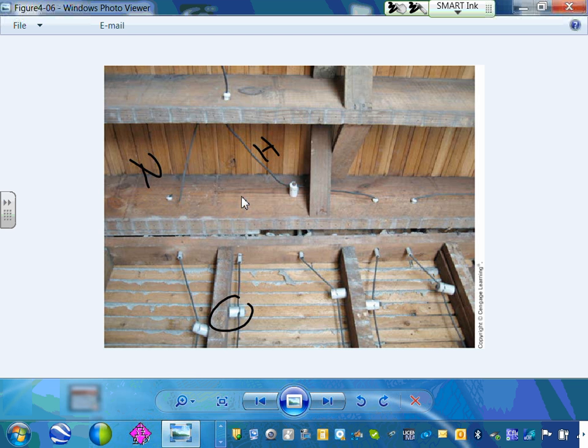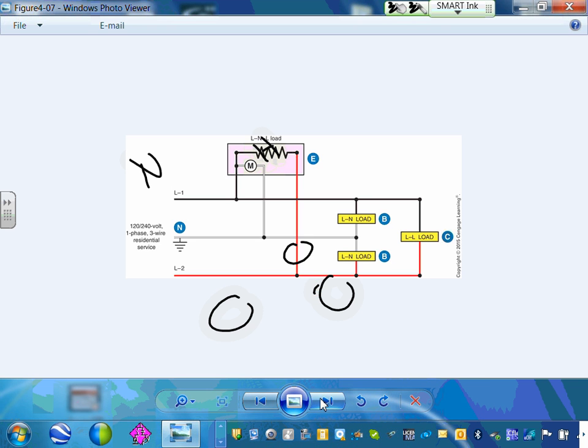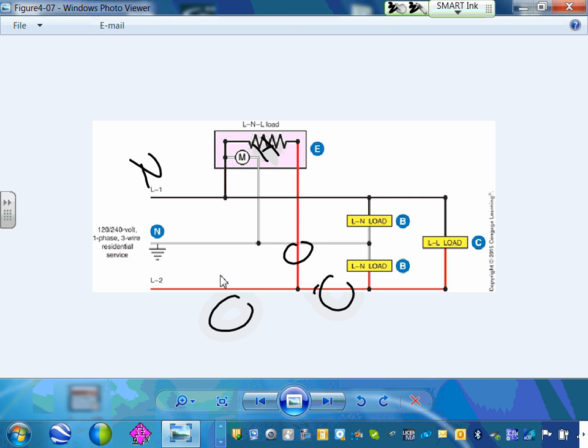But here's the knob and tube. It goes through that tube from point to point, and it sits on a knob here. What the violation is, the code says right now the hot and neutral must be in the same cable. Can you see that? That's a major violation of the code because of inductive heat and what not. So we don't wire from this wiring system, but be aware that it exists.